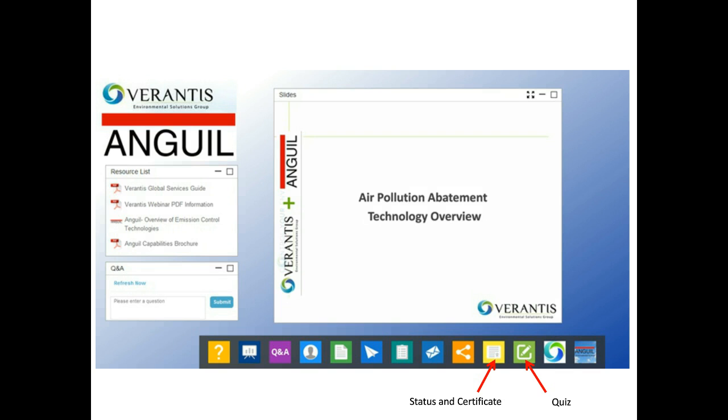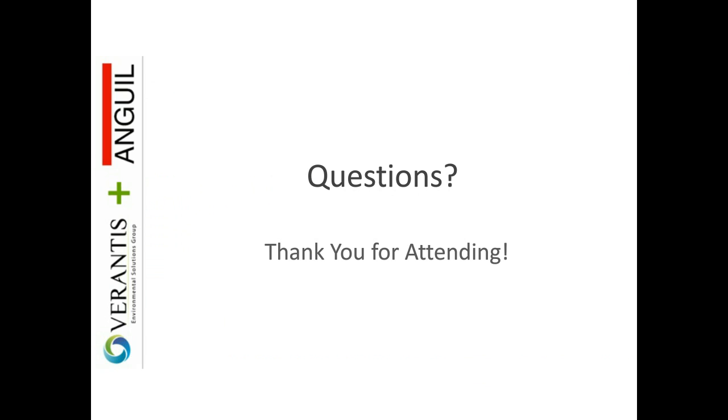One is on the lower airflow volumes I'd mentioned. So I would say, again, below 5,000 CFM, really around 3,000 CFM and below for sure, you would look at a catalytic unit. The main reason there is the RTO will still use less fuel and will have a lower overall operating cost, but the savings is so low that it won't offset the capital cost. The catalytic unit will be less expensive in those flow ranges.